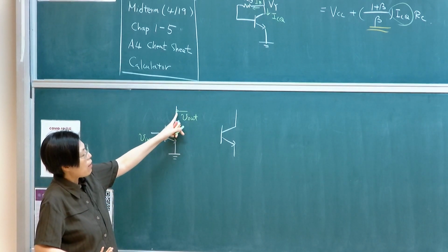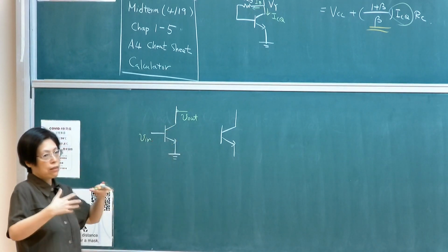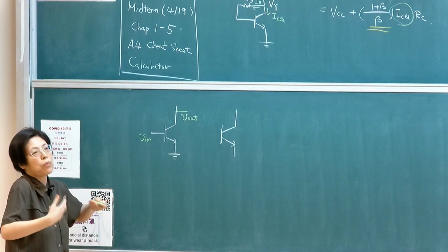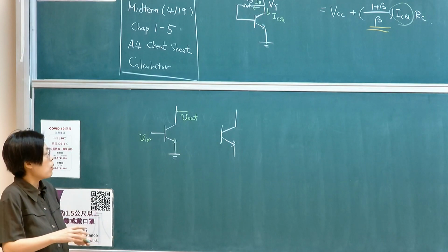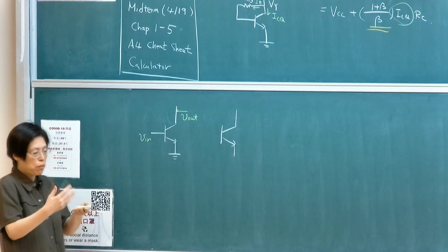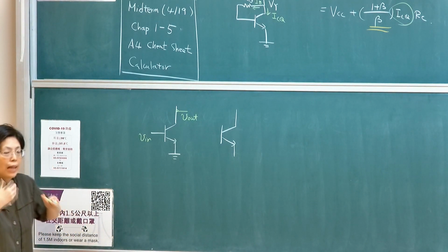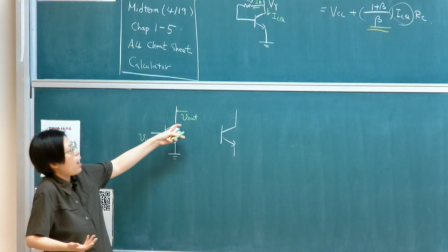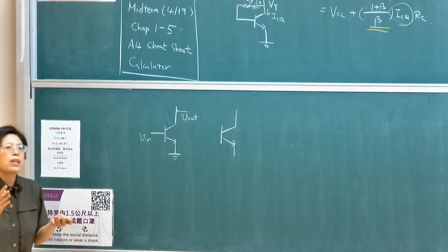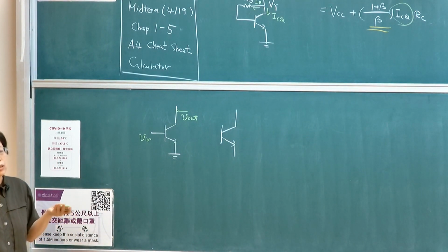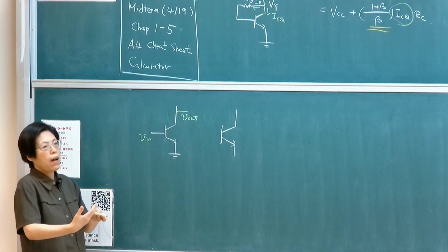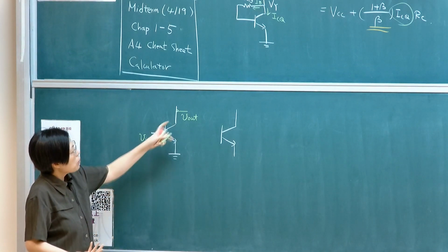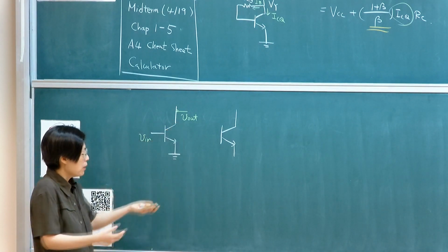Therefore, you typically want your output terminal at what we refer to as the high impedance node. We'll talk about that a little more, but get a sense that the output terminal is typical for voltage manipulation. You want your output terminal to have relatively high impedance in order to provide significant gain. So the collector is typically the output.